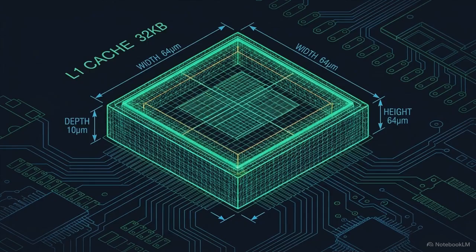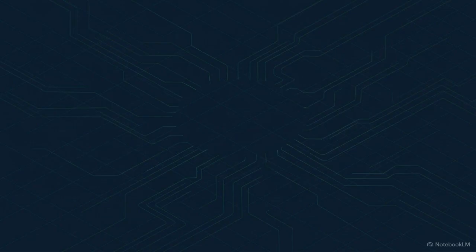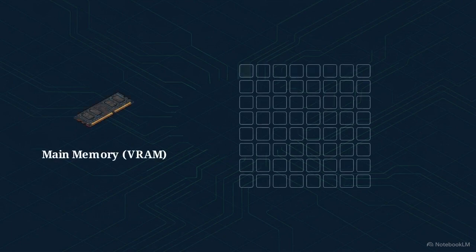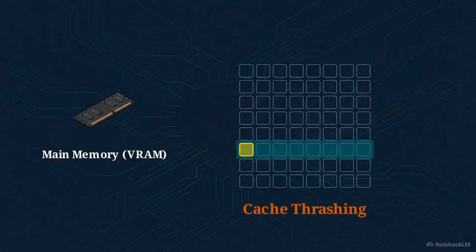Hardware does not fetch single bytes from RAM. Instead, it pulls 64-byte chunks of data into local cache lines. This grid shows the cache thrashing caused by naive row-column matrix multiplication. Standard traversal forces the CPU to jump across memory addresses, triggering constant cache misses.